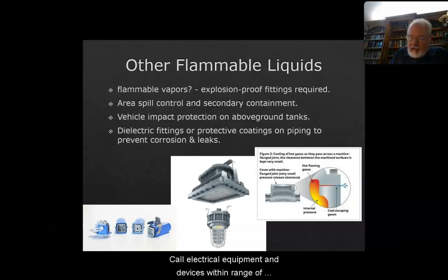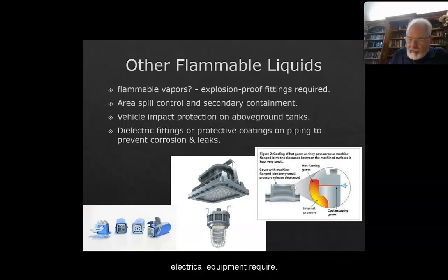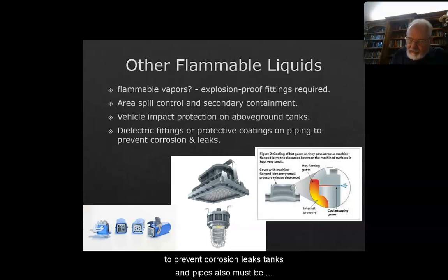All electrical equipment and devices within range of flammable liquid vapors require protection with explosion-proof fittings as prescribed in the National Electric Code or NFPA 70. If flammable vapors are present, explosion-proof fittings on electrical equipment are required. The area must have spill control and secondary containment systems. Vehicle impact protection should be provided on above-ground tanks. Dielectric fittings or protective coatings on piping to prevent corrosion and leaks.